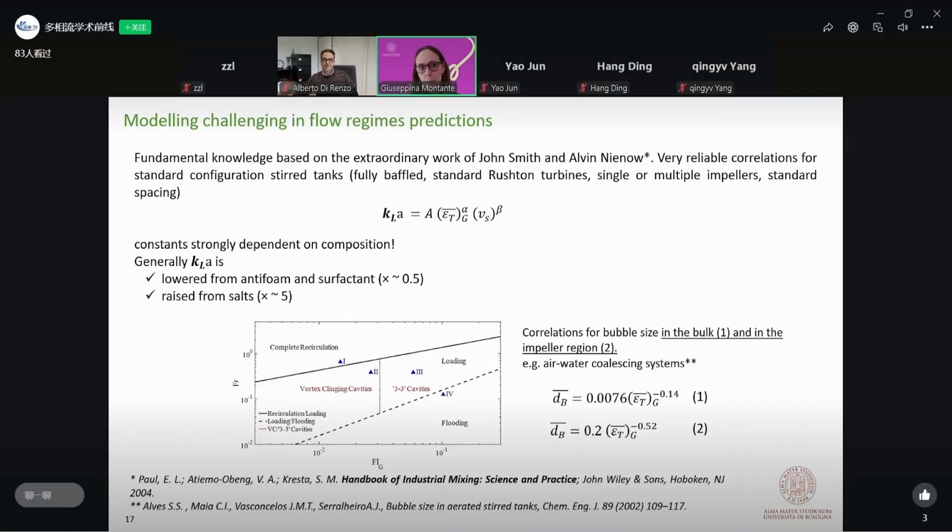So having the capability to introduce these physical aspects inside the RANS simulation is currently not possible, and in this area it's very interesting to go to multi-scale modeling, looking at the bubble size simulation first, and deriving information from this bubble size level simulation, possibly by DNS simulation, and moving to the RANS.